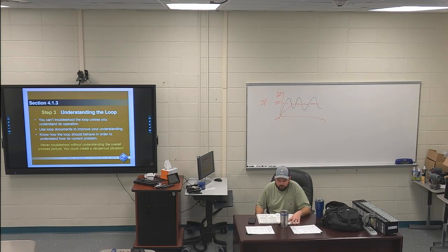Nothing in 421 or 422. I'm going to have you read through those on your own. 423, identifying possible causes of the problem. The paragraph that's after the bullet points, first 2 sentences. You're going to have a couple questions that come out of the first 2 sentences of that paragraph in the bottom left of 25. Controller operation is the easiest and most likely initial check to make. A controller can often be ruled out as a cause of the problem simply by shifting it into manual and observing the controller and its process response.